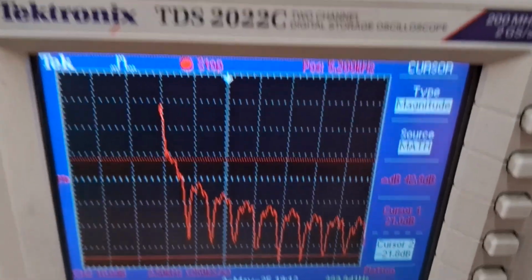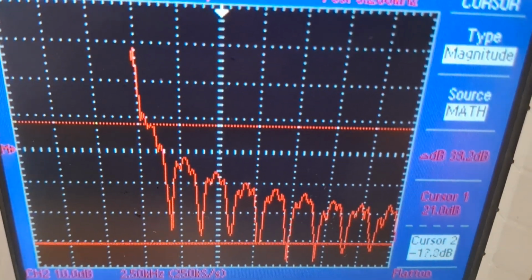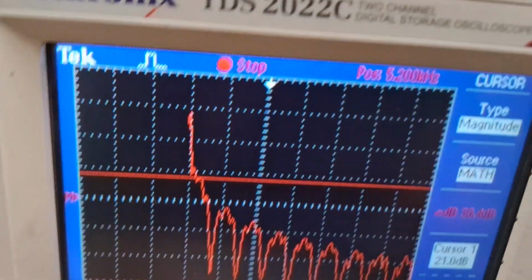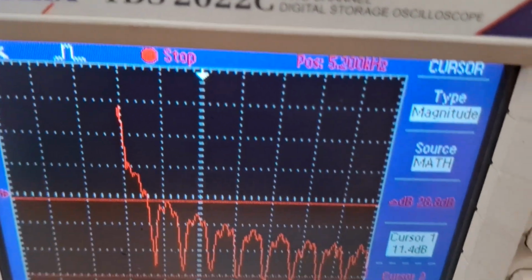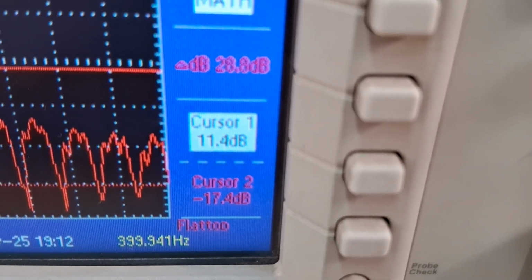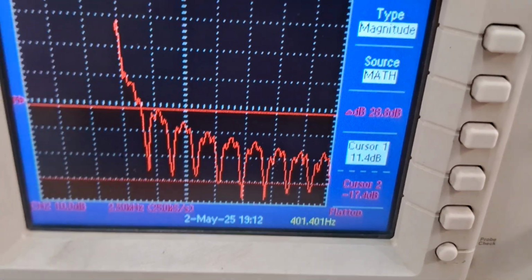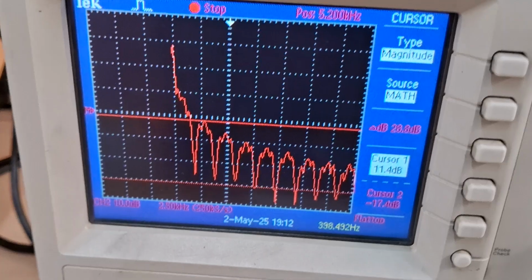Again for the second, that is the sync pulse, which you can measure, don't change the reference, sorry, and then bring the first cursor to the second position of the sync pulse, and you can take down the dB value of the second pulse, that is 28 dB something, you can note down. So you have the notation. This is how you observe the spectrum for the line codes, right?